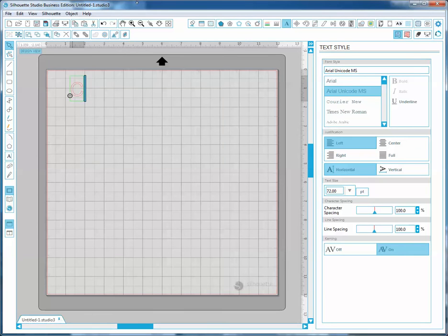So I'm going to make one that is Control C. So right now as I type, you'll see that there is a red outline around the letters, and then the letters are just blank. So the red line is the cut line. That's the line that will be cut out by the machine. And whatever the color would be, whatever material you put into the Cameo would be your color.